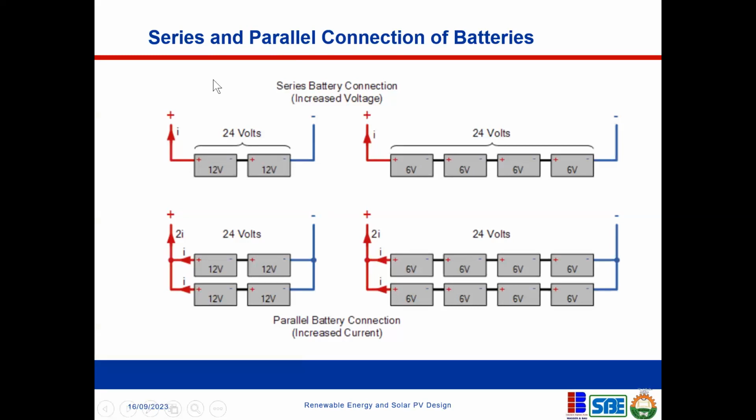So this is it here. If you have a 12-volt battery and your inverter is a 24-volt inverter, you need to connect two batteries in series to get 24. So this is how you connect these two batteries in series to get 24. These are the terminals you actually take into your inverter, and not from a single terminal. So this is how you connect in series.